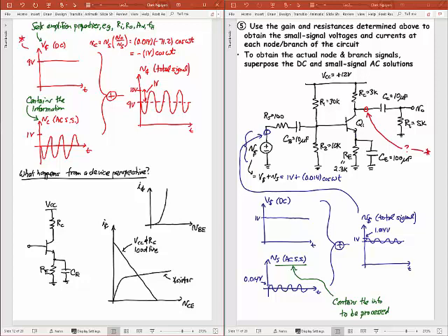That's minus 71.2. Multiply these 2 together, I get minus 1 volts. Okay, obviously I designed this problem to come to 1 volt, right? So that's minus 1 volt times cosine omega t. So where the input was a cosine, the output is a minus cosine, which I'm drawing right here. It has a 1 volt amplitude, right? So it actually is not that small a signal. The input definitely was a small signal.